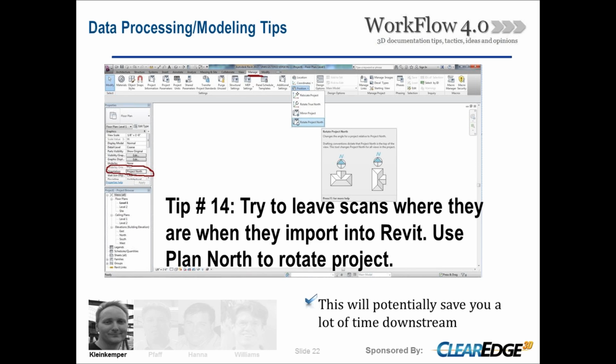Great. So tip 14, I know a lot of people want to bring those scans in and then rotate them so that the longest direction is sort of horizontal and it's somewhat plan north. It's best to actually use rotate project north. Under manage in the Revit pull down, you'll see position, and at position there's rotate project north.